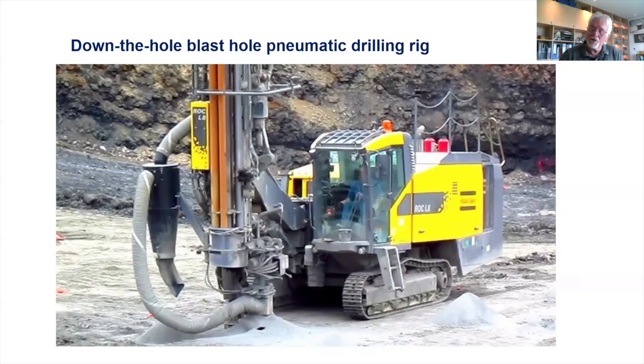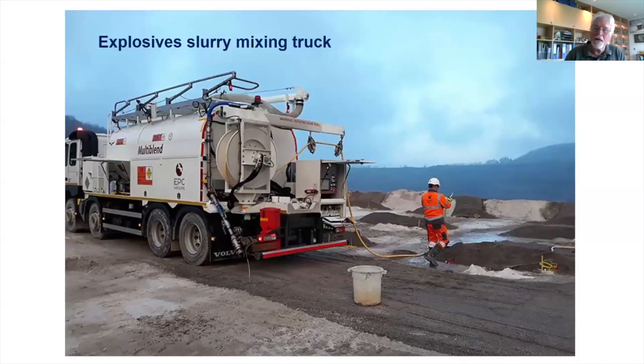So you drill these holes at a slight angle, and then we pump them full of explosives. I used to do this back in the day when I was training, and it's great fun. At the end of the day, you press a button and the earth moves, and you push the rock forward. It's a very controlled explosion. The detonations are set microseconds apart in a pattern, so that you blast the middle out and then further and further out, so that you don't cut the blasting wire from your first detonation.